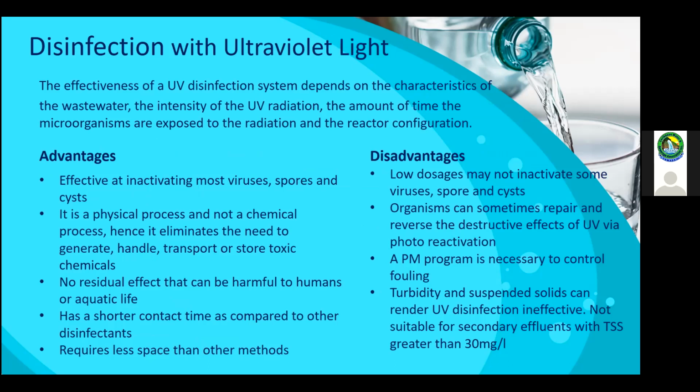Again, the effectiveness of your UV disinfection system will depend on characteristics of your wastewater, like the intensity of your radiation, the amount of time the microorganisms are exposed to the radiation, and the reactor configuration. Similar to chlorination: concentration, contact time, characteristics of the wastewater. So water or wastewater, it's the same thing. There are several unique advantages and disadvantages of ultraviolet light.